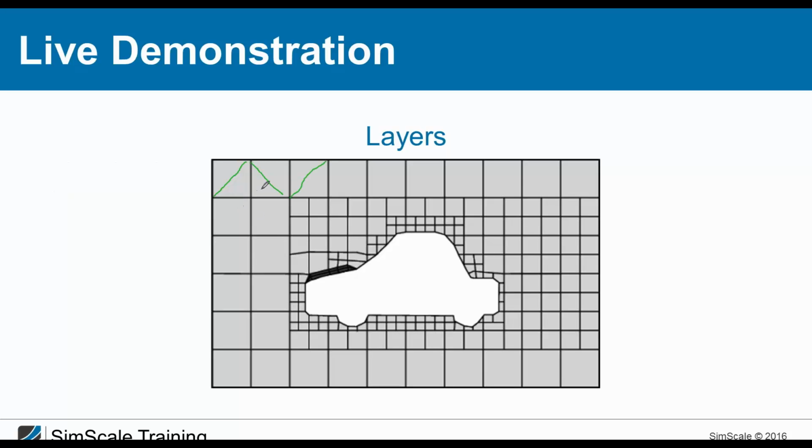For sure, that means you would also have twice the values. But generally speaking, tet meshing is easier because it's easier to approximate a complex shape with tetrahedral elements, but the result quality, for numerical and mathematical reasons, of a hex element is better. Therefore, I suggest using hex elements for CFD all the time.